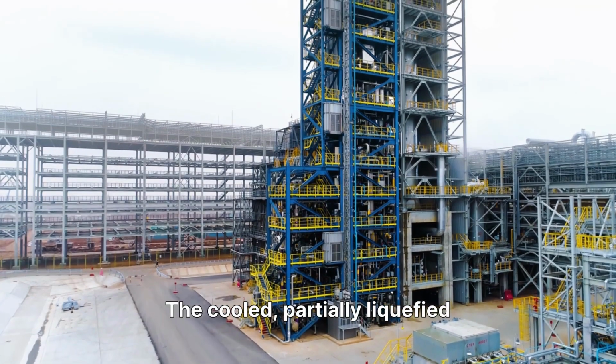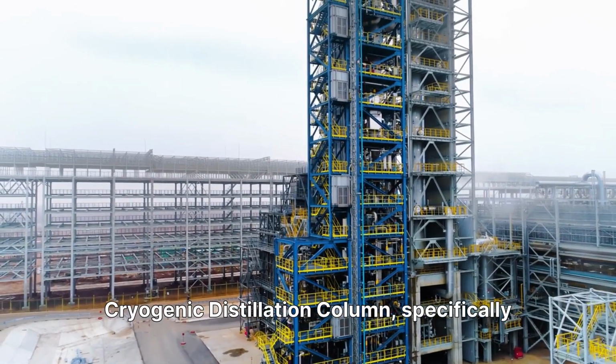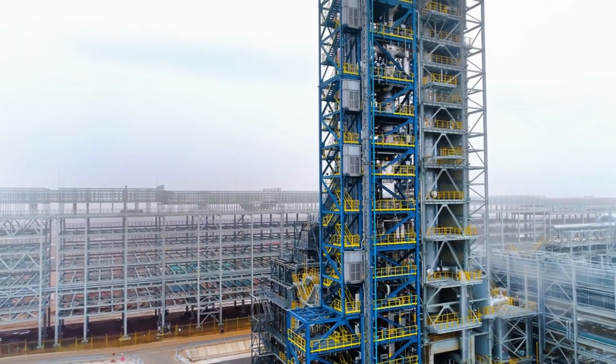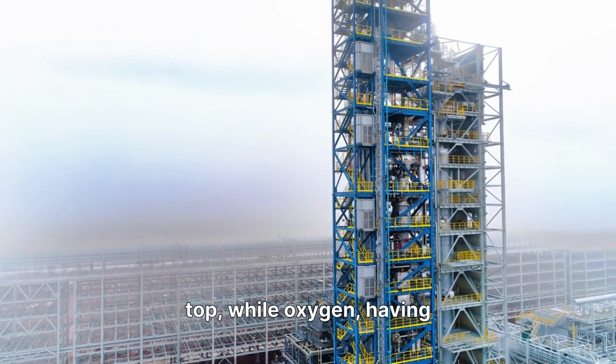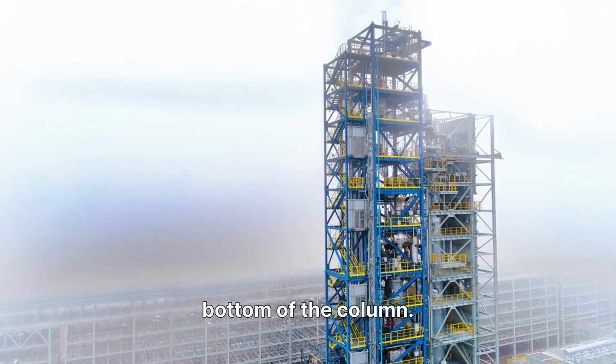The cooled, partially liquefied air then enters the cryogenic distillation column, specifically the high-pressure column. Inside this column, nitrogen, with its lower boiling point, begins to vaporize and rise towards the top, while oxygen, having a higher boiling point, condenses and collects as a liquid at the bottom of the column.